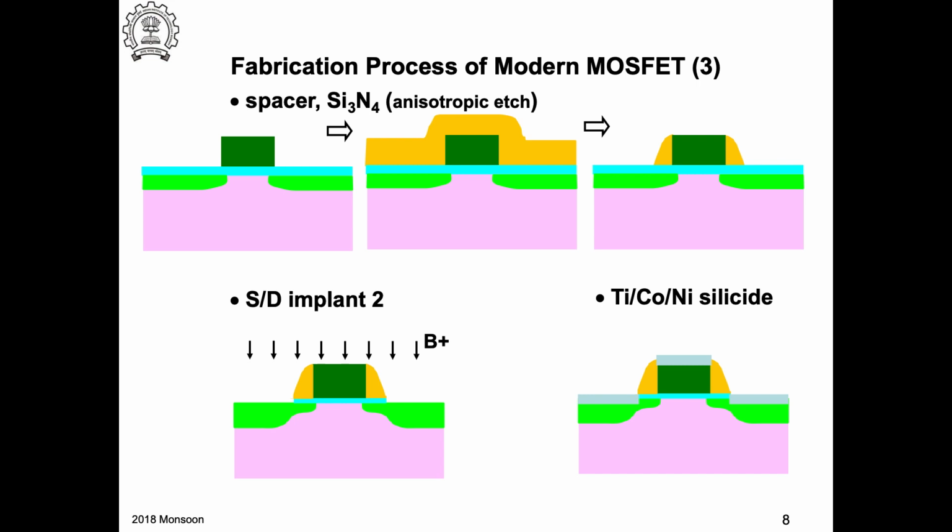See, it doesn't have to be very thin, because usually the concentration of boron in the source drain would be in the range of 10 raised to 20 per centimeter cube. But here you would have N-type dopants because of the P-channel transistor, and the doping concentration will be in the range of 10 raised to 17 to 10 raised to 18. So 2 to 3 orders of magnitude smaller. So the residual, the tail of this profile that gets into the silicon with this boron implant. So you are talking about a P concentration of 10 raised to 20, and then a tail that is 10 raised to 17, for example, right?